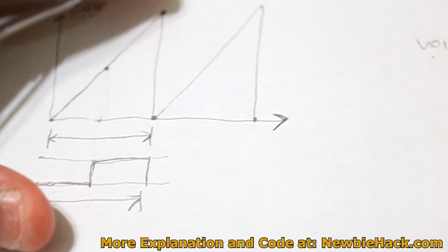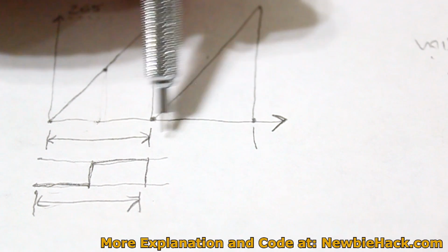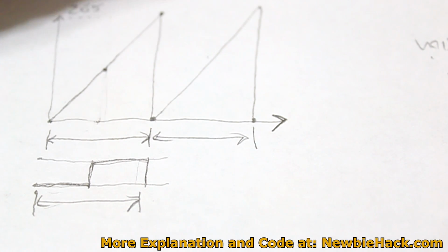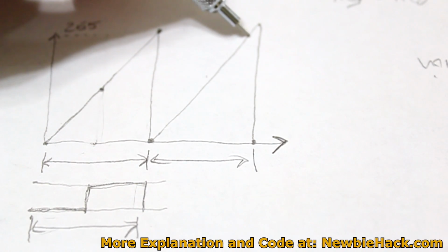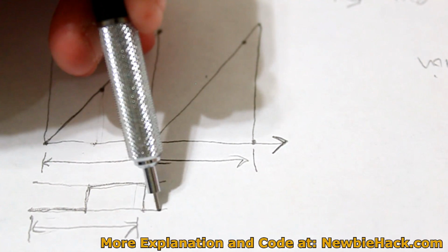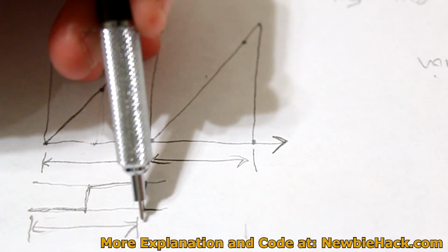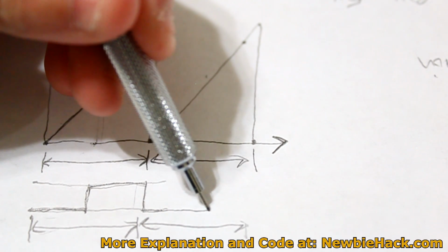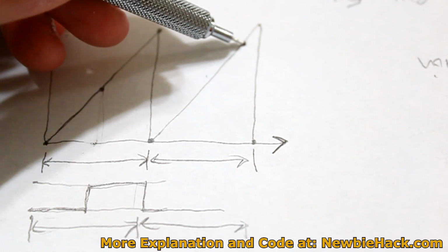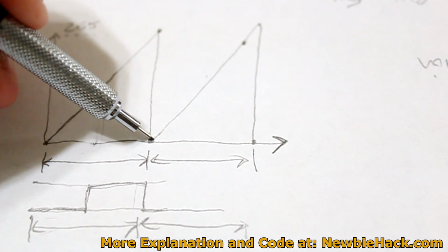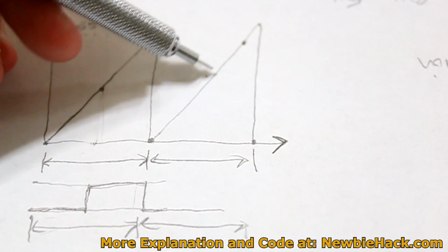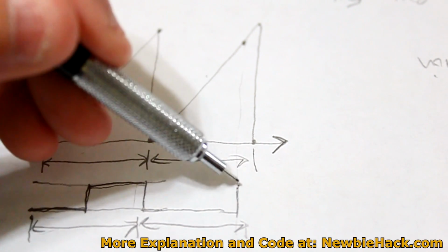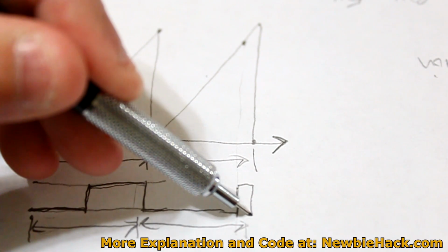Now if you wanted the next period to be a little bit of a smaller pulse, let's say we wanted the pulse to happen at 200, then the pulse width would look something like this. It would continue going from 0 volts and keep going until the counter got to 200, because it's counting 1, 2, 3, 4, 5, 6, 7, all the way to 200, and then it will jump to 5 volts at that point, go over, and then jump back down.